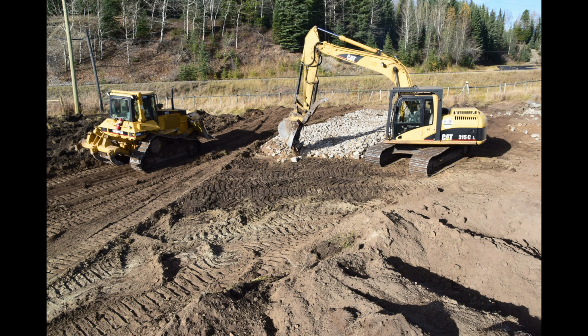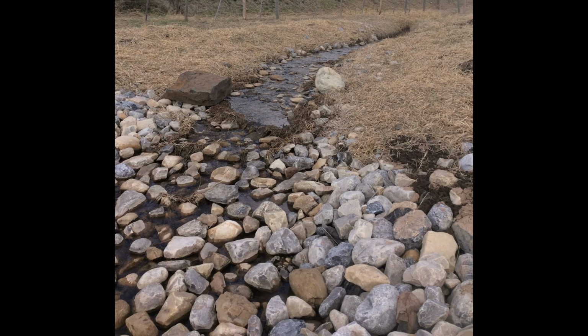We found it almost impossible to push the rock into the dry, silt texture soil. We had to first loosen the surface of the ground with a bucket on the excavator, spread the rock, and then run over the rock with the tracks on the excavator, and then sprinkle soil between the rocks using the bucket on the excavator. The loosened silt was like powder that would not compact, and the wet silt became stickier than glue. We watched with great concern as soil washed away because of water flowing in the spillways.